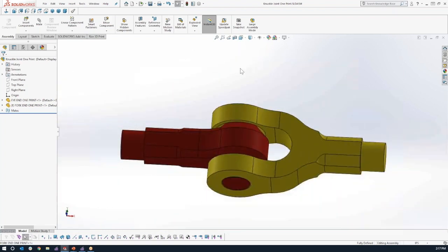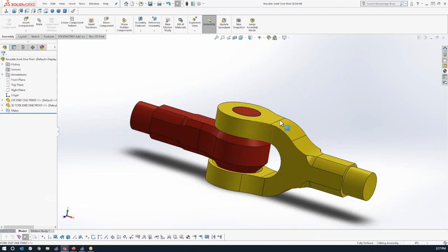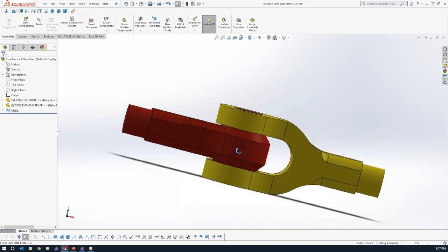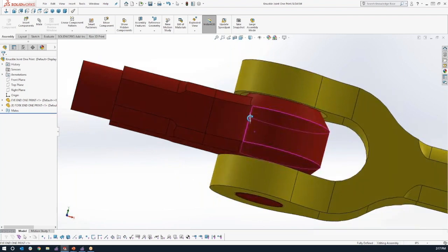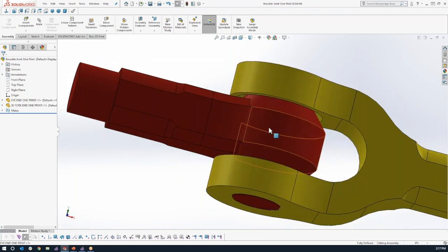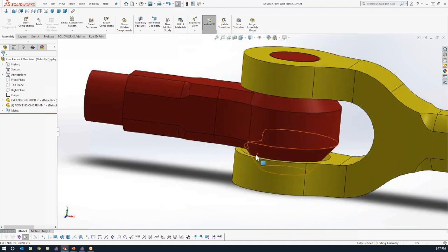And I've also made both of them land flat on the bottom of the build plate, so that as they print, they don't need to touch each other except at a few places where the support will build under those overhangs here. But that support will be much easier to remove than if you tried to do a similar thing without these self-supporting build angles.